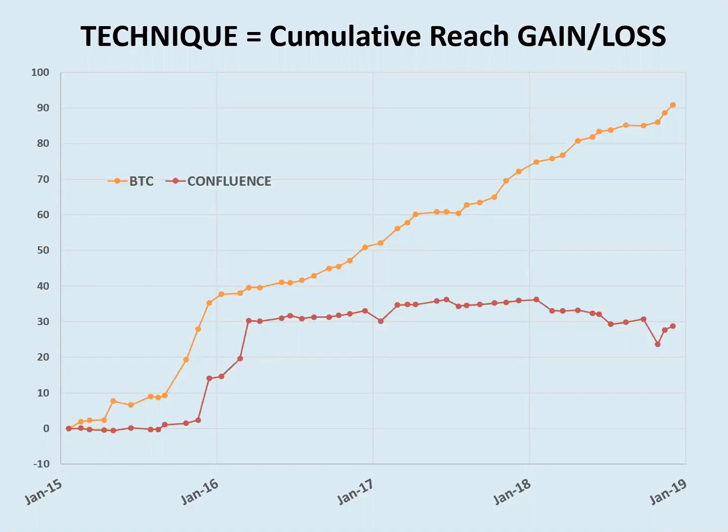So do the same thing for that downstream reach, the confluence reach, but then you take each of those monthly gains or losses and you start to just add them sequentially. So it's accumulation of whether it's gaining or losing. And the importance of that is if it's tending to lose concentration for some reason, then these slopes will be negative. If it's always gaining, then the slope will always be positive. I hope that makes sense. That's kind of a lot to describe.